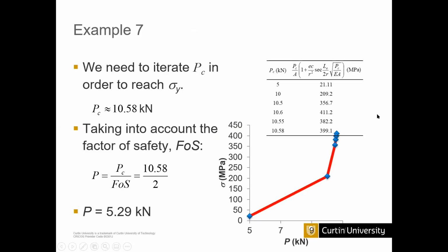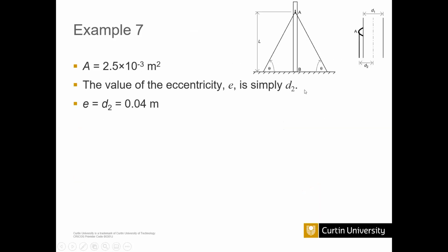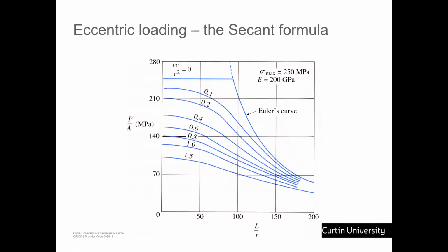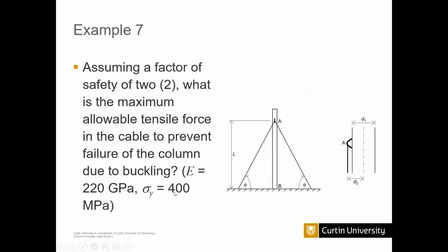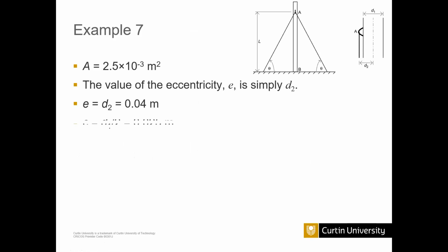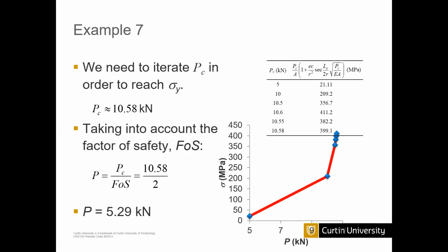so you have this equation and you can find out different values, and in here PC value 10, 58, because with the sigma y, because we know the yield value, the yield stress is provided. So with the yield stress you can match with these values. So you can see in between these two values it will reach the yield stress. I didn't remember the values. Let me check. What is the yield stress? They provide it. Yeah, 400. So 400. Yeah, it should be between these two.